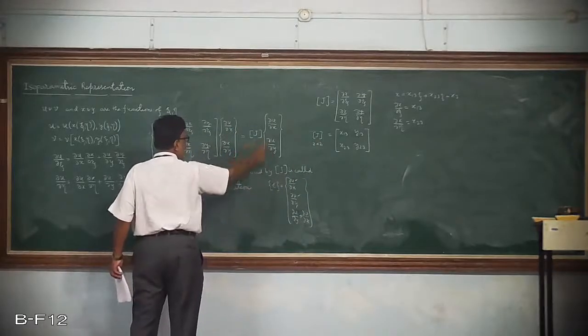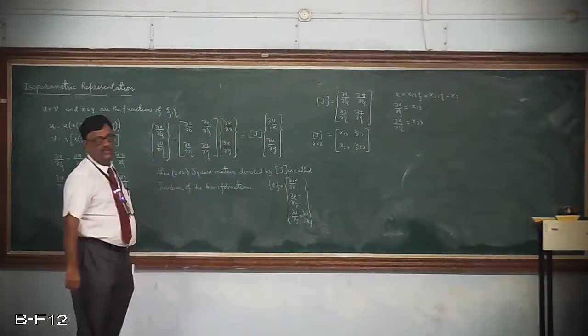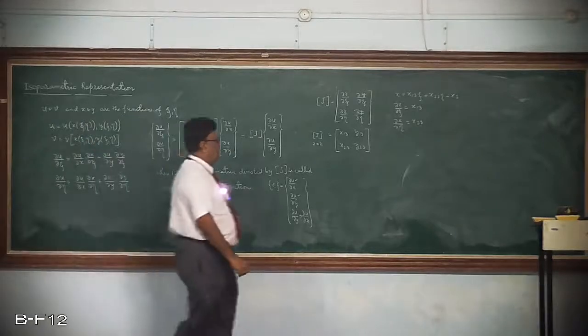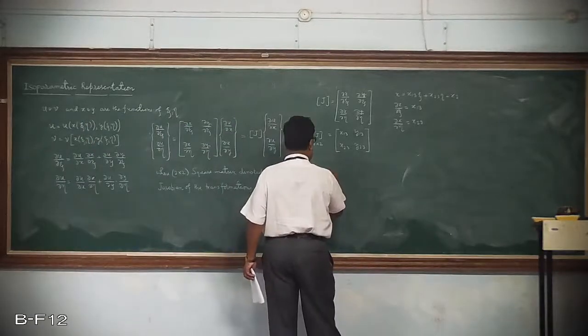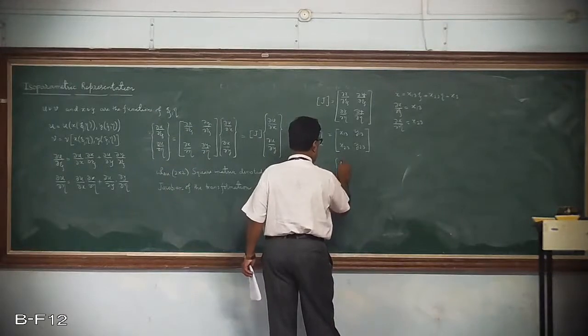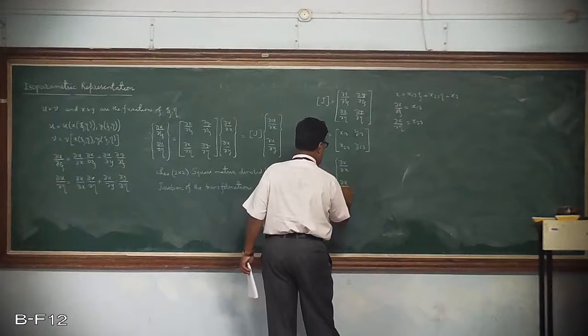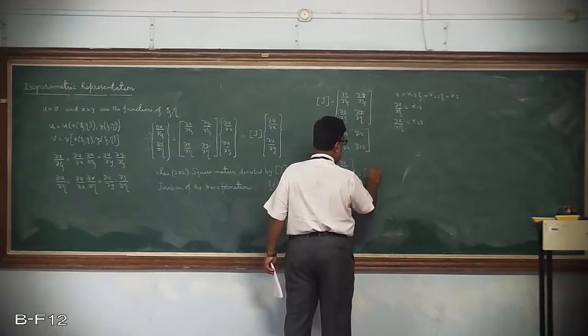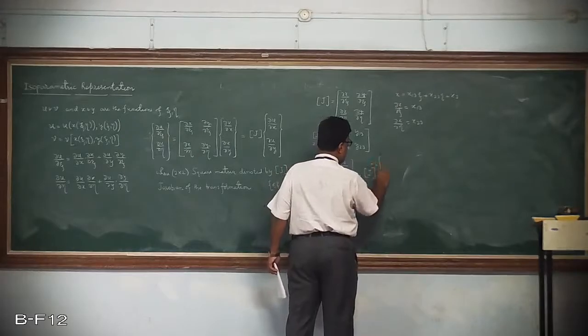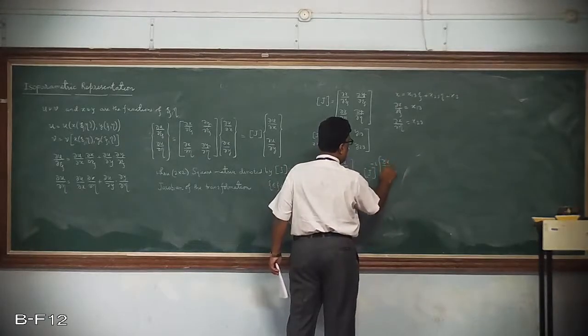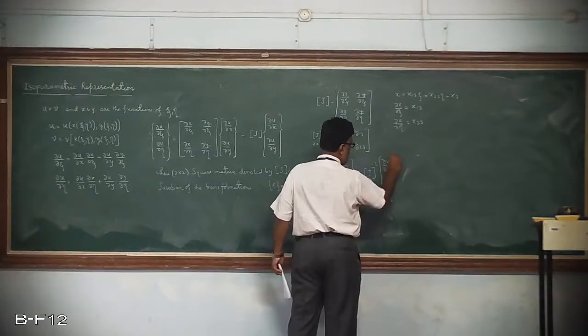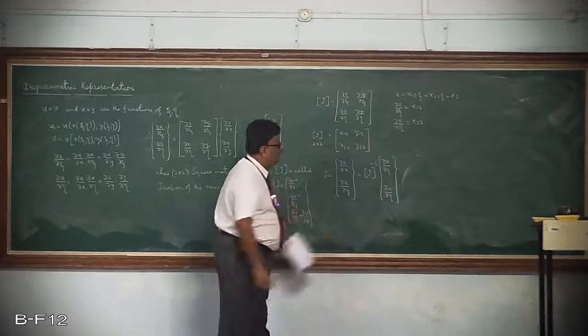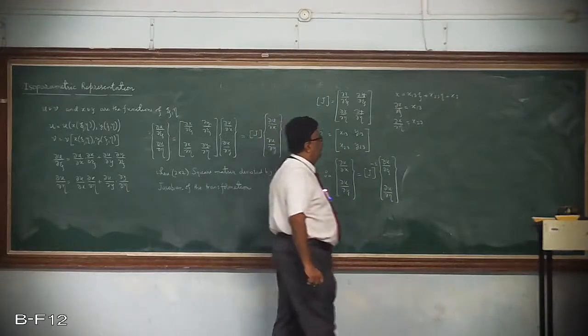So naturally, to get this, I have to take the inverse of the Jacobian matrix. Therefore, if I want ∂u/∂x and ∂u/∂y, I have to take the inverse of the matrix. So this is ∂u/∂ζ, and this is ∂u/∂η. So this is what you will get.